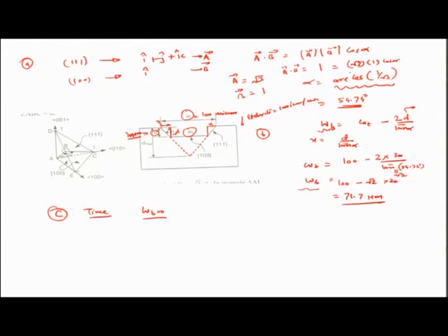So we can assume that once it closes, or WB becomes 0, the etch would typically stop, because 1 1 1 again is the slowest etch rate in terms of the different planes and orientations that the silicon might have. So corresponding to WB equal to 0, if we use the same equation as above, we have a d value which emerges, which is equal to Wt tan alpha divided by 2, and this being 100 microns, times root 2 by 2. So this becomes 100 by root 2.